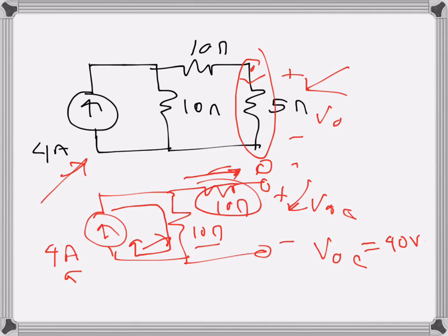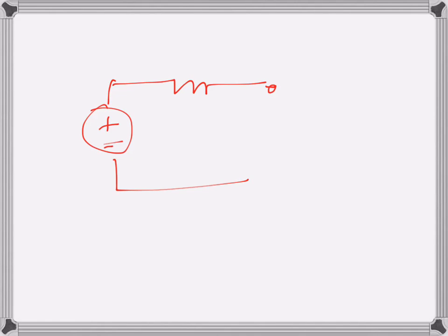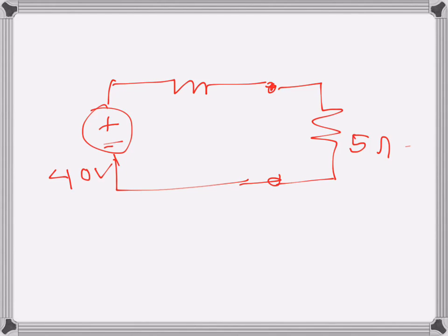So we have now our circuit. We can replace this entire part by one voltage source, which is Thevenin's voltage source, and this one is a resistance, and we will connect our resistance, for which we have found the Thevenin circuit, which is 5 ohms. We calculated the Thevenin's voltage to be 40 volts and resistance to be 20 ohms.